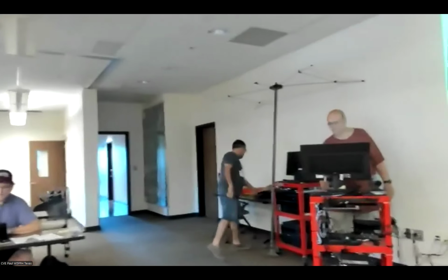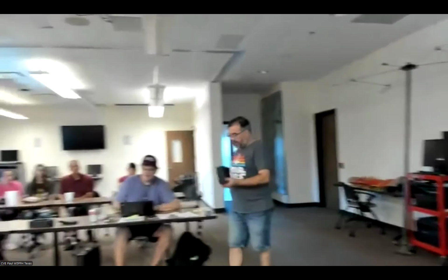These are 35% infill, and the 2 pieces took 6 hours together. And then I created a dock for it as well, so that when they drop it in the dock, not only does it interface with the PC, but I also have it set up for wireless charging. So they're not having to plug a cable in to charge the battery internally. Because of all the channels, the grooves, I had to put in spacing for the grommet, and built inside of it, I actually have air channels on it to help prevent the heat from everything else.